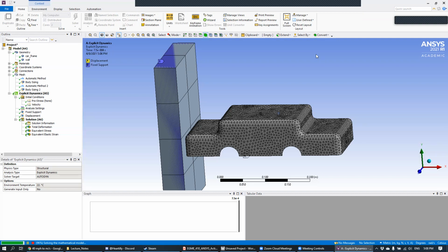That's a problem you're personally interested in, and something where you obviously don't want to destroy your chassis to find out. I just didn't know if that was too simple for a simulation. No, that's perfect. I think the complexity for you would probably be in meshing it, because that's the thing most people struggle with: you have this fairly complicated CAD, and meshing it the right way and getting it to fit within the student version. I think that's going to be the main challenge for most people. So yeah, I think that's perfect.